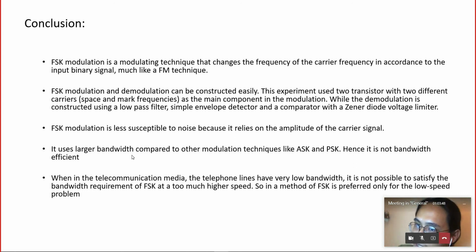Since the FSK uses many different frequencies of the carrier signal, it occupies a larger bandwidth. In telecommunication media, the telephone lines have very low bandwidth. It is not possible to satisfy the bandwidth requirement of FSK at a much higher speed. So the method of FSK is preferred only for low speed applications.